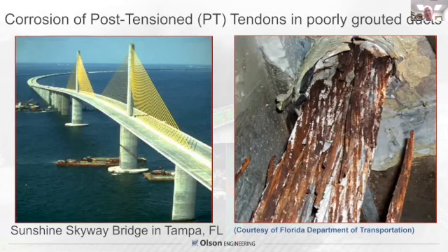So having said that, one of the other problems of the project, because it was older, is there was concerns about voided versus grouted ducts. If it's not well grouted, that can lead to post-tension corrosion. This was first discovered in the United States in the late 80s by the Florida Department of Transportation, and Teddy Theryo was involved in this project with Parsons Brinckerhoff at that time, and it's now WSP, at the Sunshine Skyway Bridge in Tampa, Florida. You might have thought the corrosion was in the girders, which were also post-tension.